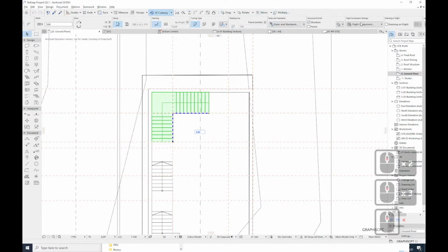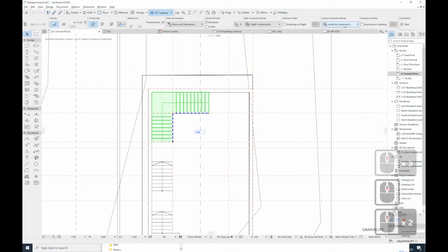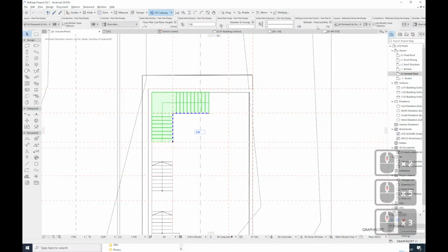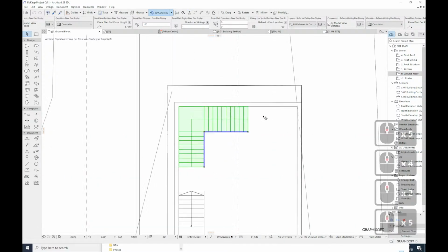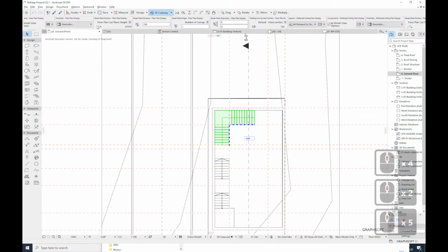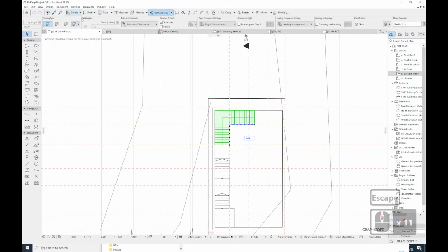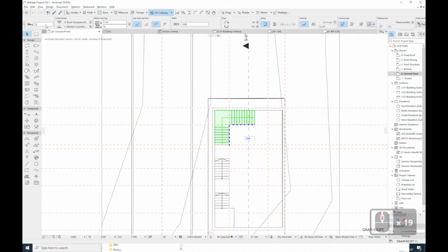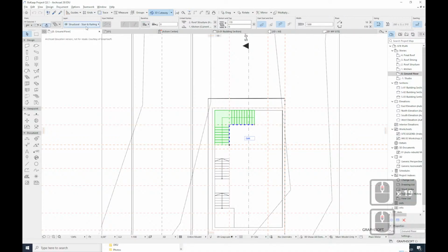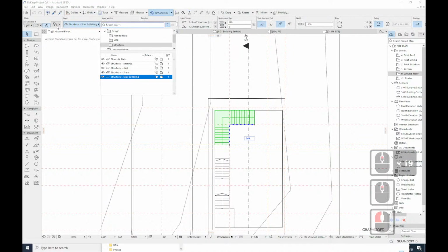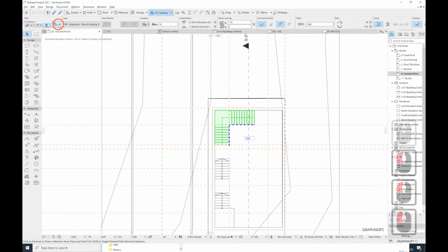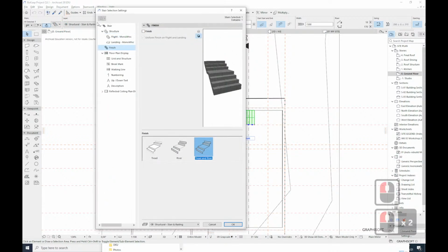You can switch off the annotation for the stairs so it's not visible, and there's a way that you can make these things visible only in a certain plan. Let me go back there. This is very strange. If you go back to your stair, link stories, this is something else. Let's go in here. You can specify on what levels they're visible and not visible for certain stairs.